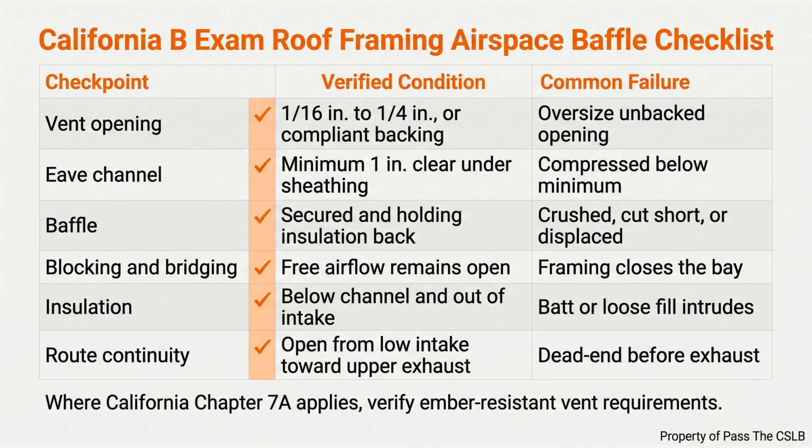One wet morning does not automatically mean structural failure. The concern is repeated or prolonged wetting. If the wood stays damp, moisture content can rise into a range that supports fungal decay, warping, and mold growth. Insulation can also lose performance when it becomes wet or when air moves through it.